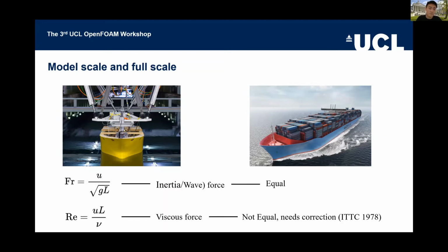This also gives us the possibility of thinking that if we have more full scale sea trial data in the future, it's always best to run CFD in full scale directly, because even if we can scale the force correctly, the fluid field will also be different because the Reynolds number is different, so the fluid behavior will be quite different too.